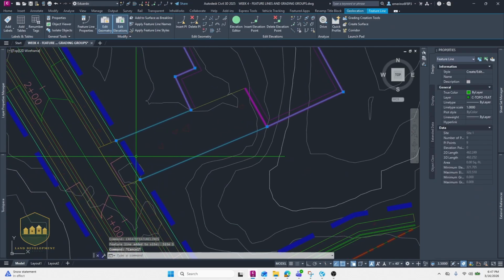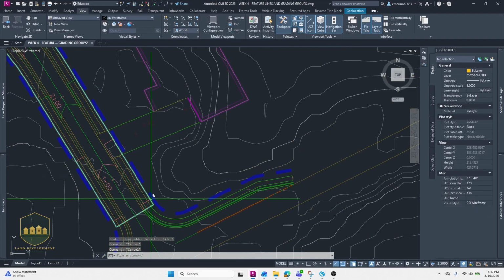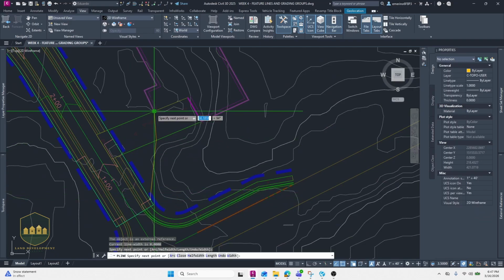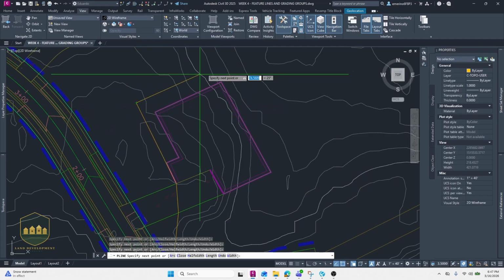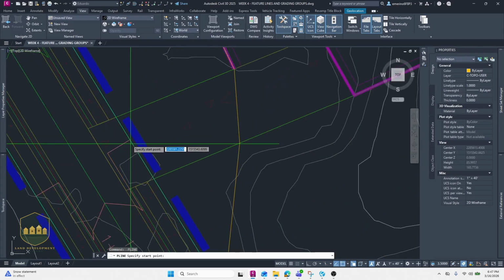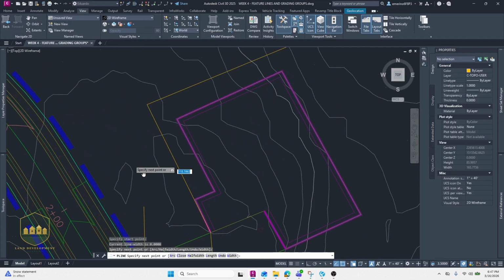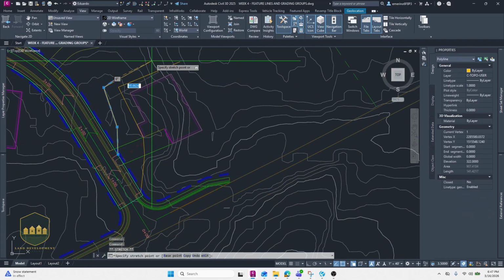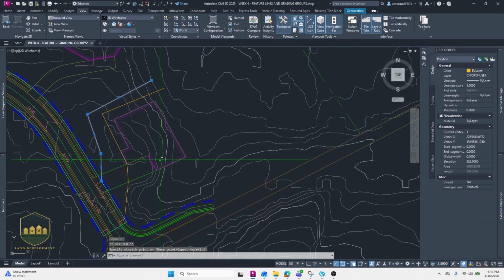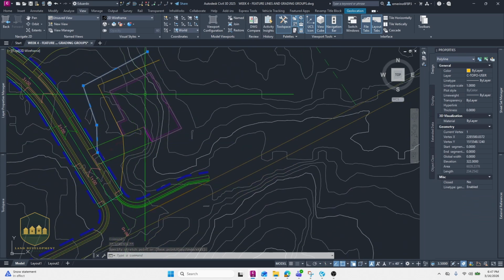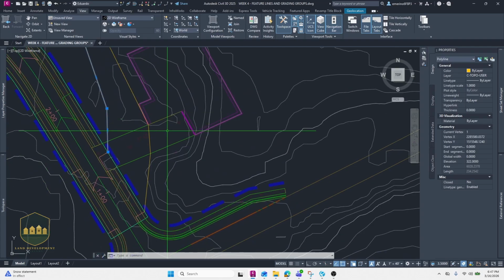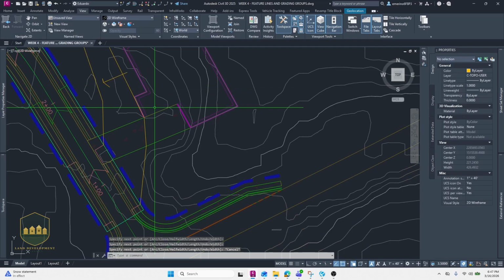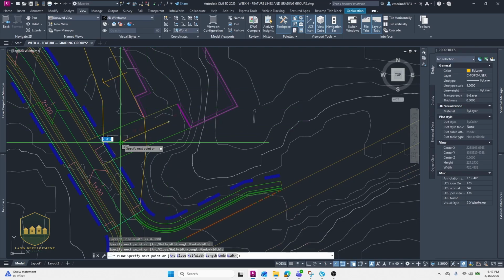And then I can just see that I want, for example, this contour to wrap around the house like this. And then it's gonna go and it's gonna shoot out this way. I also know that I want this contour to shoot out this way, and then tie up like that. And really it's gonna be more like that. The reason why I know this is because I want the house to be above the road. So water will drain this way, right? I want water to be draining away from the house.